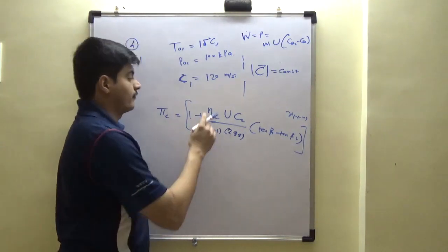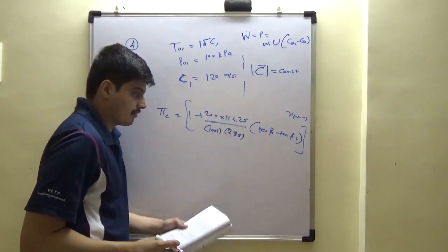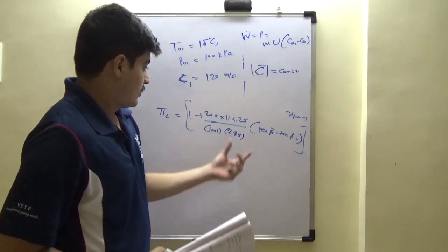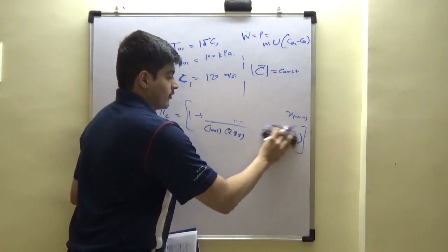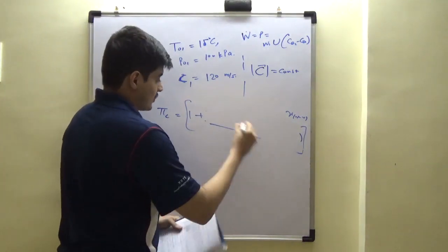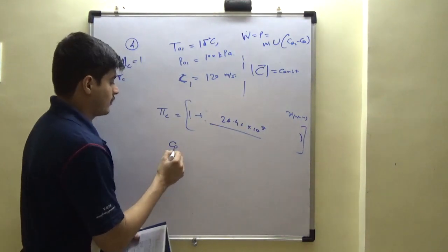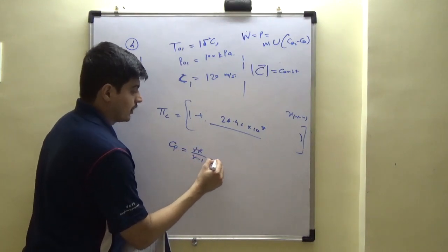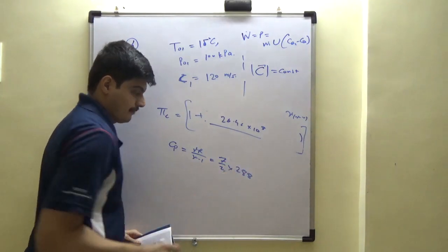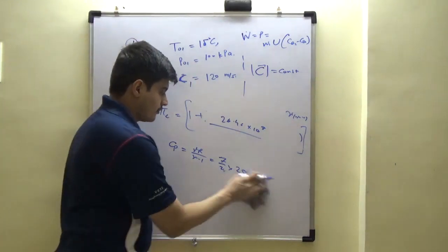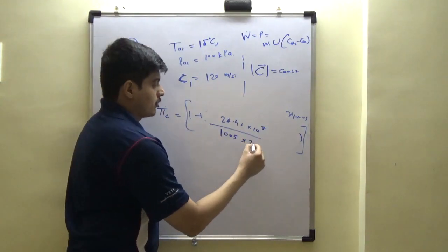Right? 1 point something. This is 1, which means this is 200 into 114.25. We have already computed this number in terms of kilowatt. So the whole thing you have to do is substitute it here: 20.46 into 10 raised to 3. If you forget Cp, how would you do it? Gamma R by gamma minus 1, 1.4 by 0.4, which is 7 by 2, into 288. Approximately the constant, or 300. So this becomes around 1005 into 288.